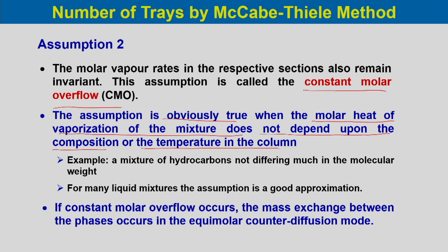If constant molar overflow occurs, the mass exchange between the phases occurs in the equimolar counter diffusion mode. So, please note that if constant molar overflow occurs, the mass exchange between the phases occurs in the equimolar counter diffusion mode. If this assumption is valid, then the mass exchange between the vapor phase and the liquid phase should be based on equimolar counter diffusion.